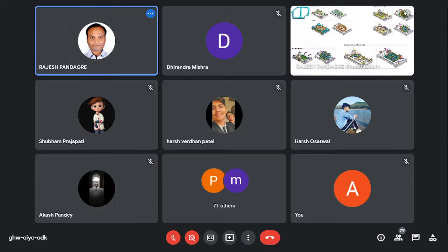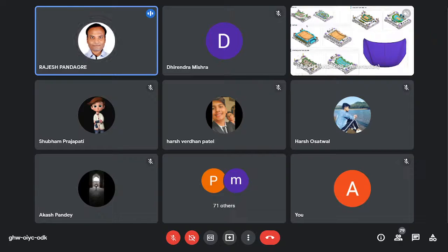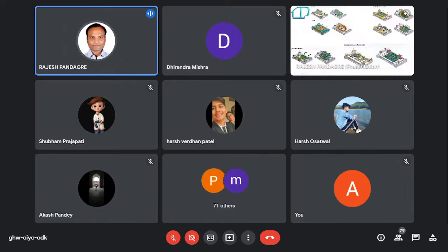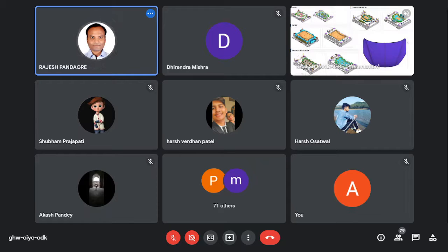What kind of analysis do we do on the Class A to get the desired shape, and nothing should be affected on Class A. One more thing before going ahead: whatever shape we have achieved, it should be properly fit and finish, which is one of the most important criteria. Fit and finish, gap and flush, these two things are most important after getting the desired shape out of all dies. So once I got this shape, now I have to put it in the die, in the press machine.